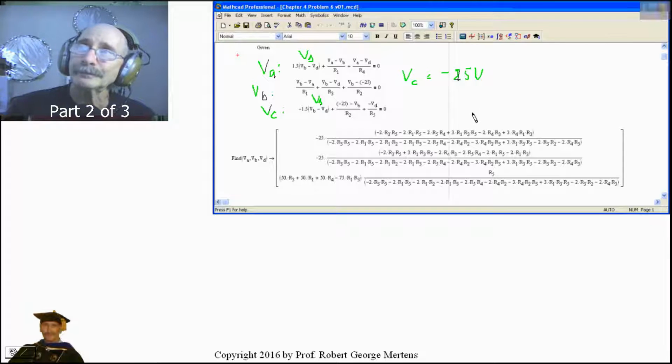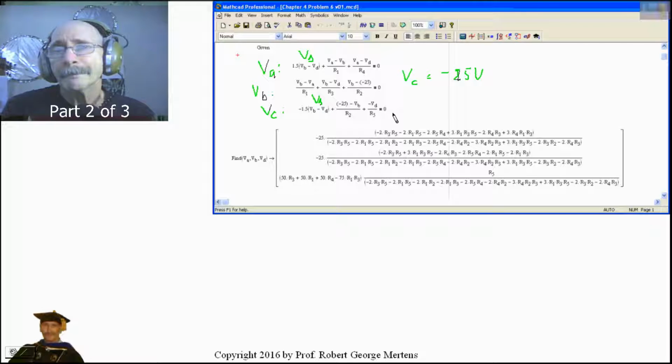Now, I know on this one we had a ground, but really it's less a ground and more of a reference. So there's no current going in or out of the ground. It's just a reference point. We're calling that point 0. The circuit is fairly standalone, so all the values of the voltages in the circuit are going to be referenced to each other. So the current going away from that point at VC was minus VD divided by R5, or 0 minus VD.